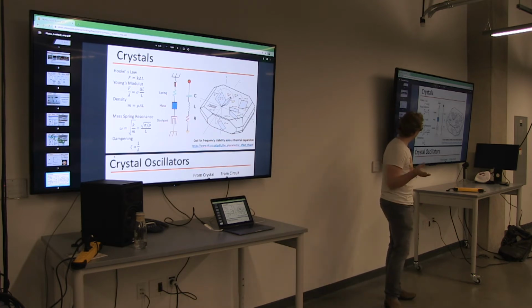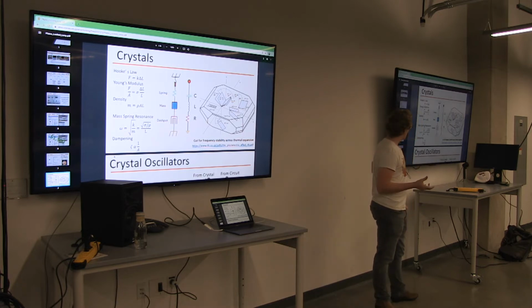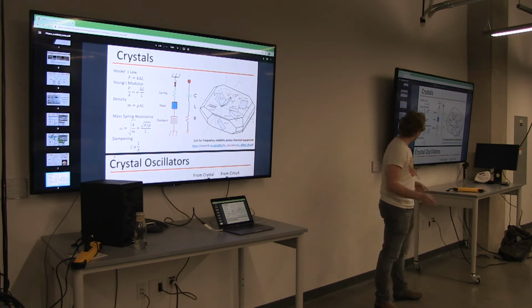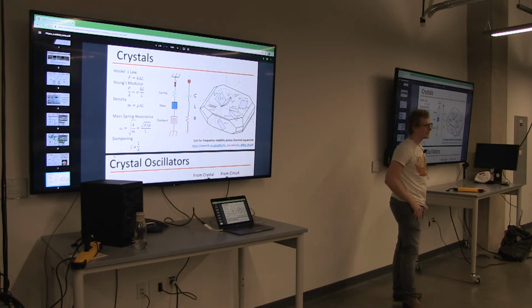And it turns out that the LCRs you see here aren't exactly what it would be in the mechanical domain versus the electrical domain, because, again, there's this electromechanical coupling in the piezoelectric effect. But the good news is that the frequency is the same, right? Because it's what's called a linear coupling. So from one domain to the other domain, it's just scaling by a constant. And so frequency is the same when you scale by a constant, but you're going to end up with a different damping factor. And then the last thing you have here is the cuts of the crystal, right?